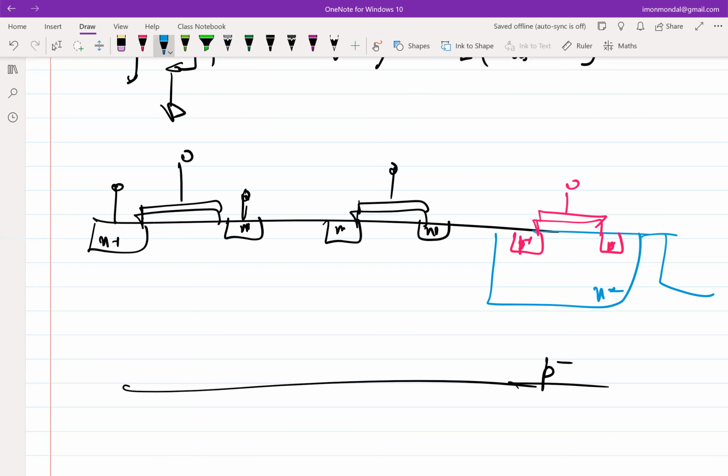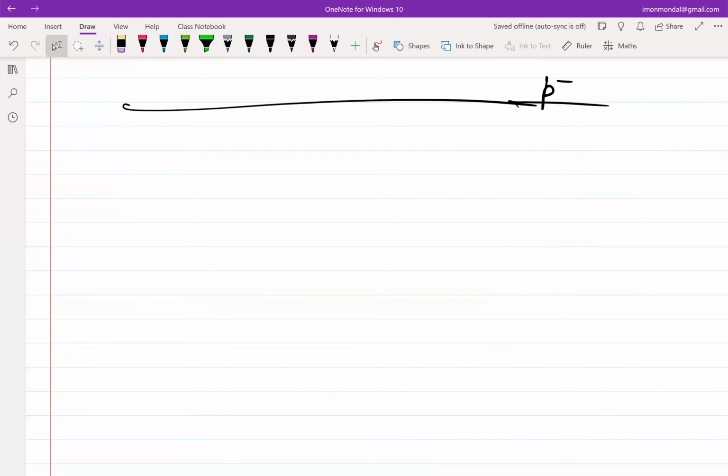I mean, in most cases they don't. But there are some processes in which they allow separate bodies for NMOS transistors. Those are called triple well processes. But anyhow, in a more generic sense, you cannot have a separate body for an NMOS transistor. So which essentially means that if you are looking at the Cascode transistor, right?